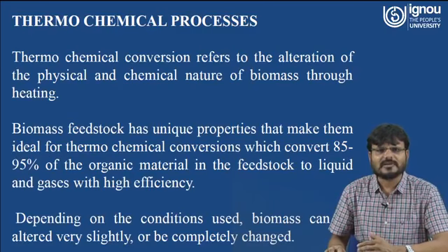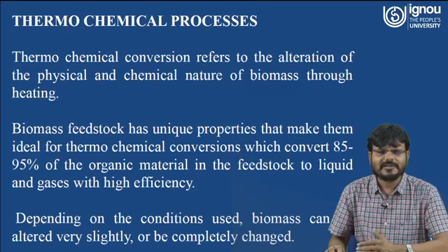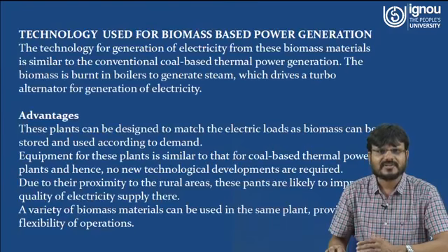Now, the third is the thermochemical process. Thermochemical processes refer to the alteration of the physical and chemical nature of the biomass through heating. Biomass feedstock has unique properties that make it ideal for thermochemical conversion, which converts 85 to 95% of the organic material in the feedstock to liquids and gases with high efficiency. Depending on the conditions used, biomass can be altered very slightly or be completely changed.